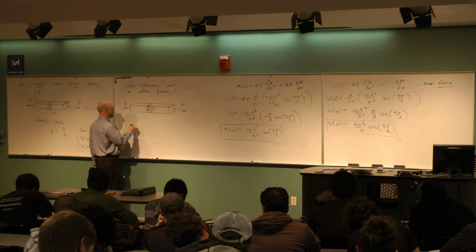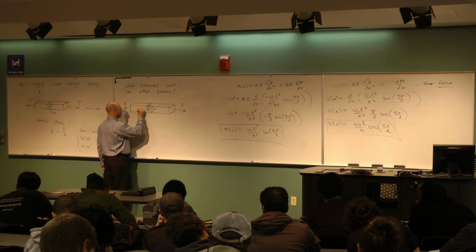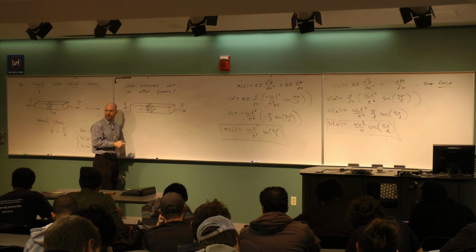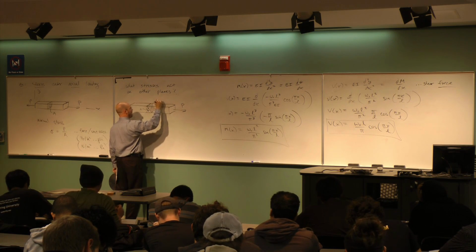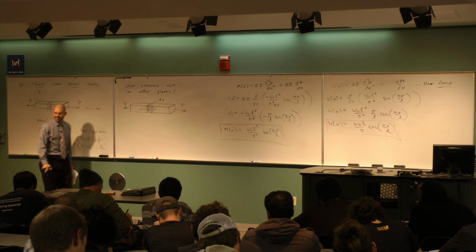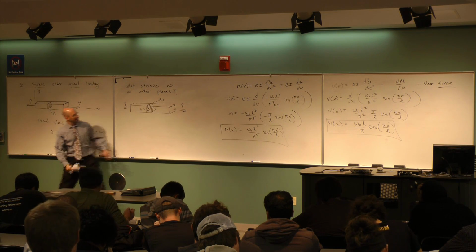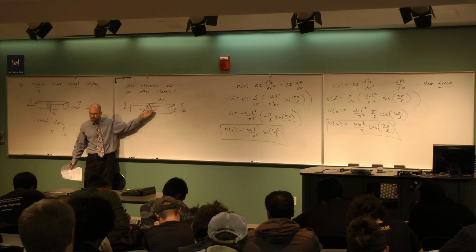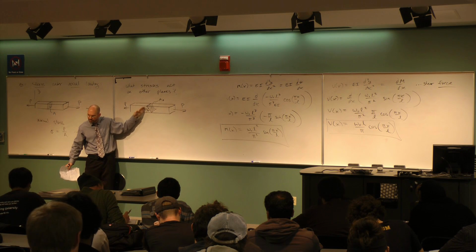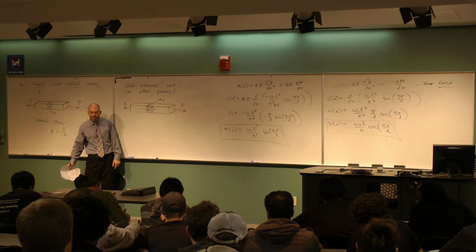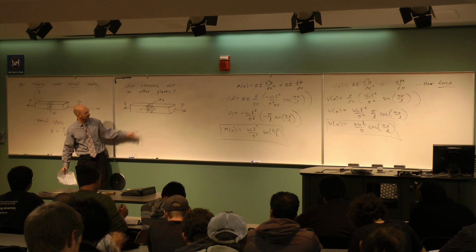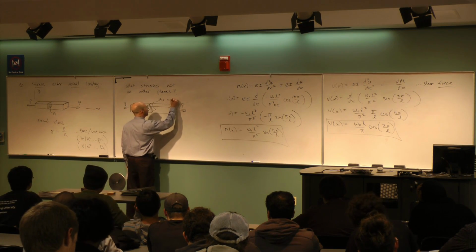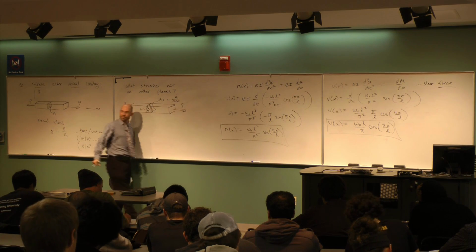Keep in mind that the original area, A, in the stress formula, is like the vertical leg of this triangle here, right? If I just multiply by the width, I'll get a vertical area. And then this guy at an angle is a different number. It's A theta. Incidentally, how does A theta compare to A? A theta is the hypotenuse area, and A is the adjacent leg area. So how are they related? It's a cosine relation. Specifically, A is A theta times the cosine of theta. So that would mean A theta is actually A divided by the cosine of theta, right?